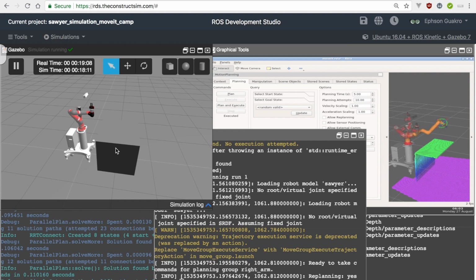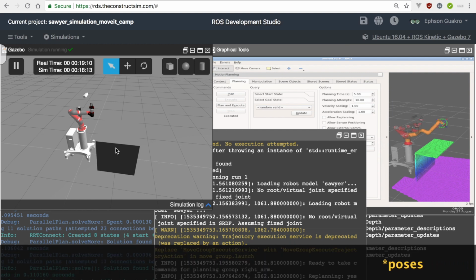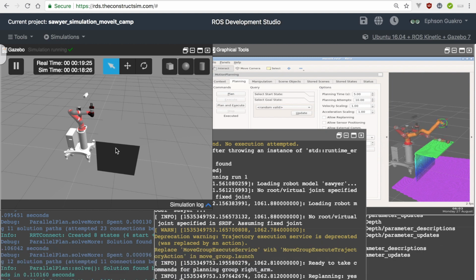You can get the pose relative to the camera frame, pass that to the end effector, and then direct the end effector to pick it up. Yeah, that's a topic for another session that we can look at. But that's it for today's session. We're using 3D perception to affect the planning inside of MoveIt.